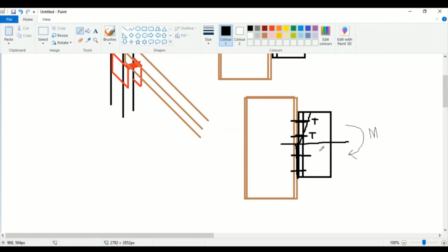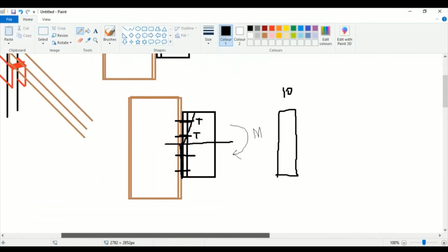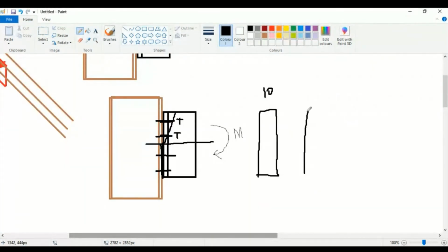Okay, so if you already have a tension, this would really subtract the effect of the tension that is already acting in that. Suppose you have an equal tension acting on it, say for example 10 kips because of the direct shear, and then suppose because of the indirect shear you have say, I don't know, 8 here, and maybe 8 here. So what will be the resultant? This is plus, this is minus, so your ultimate would be like 18 and 2.